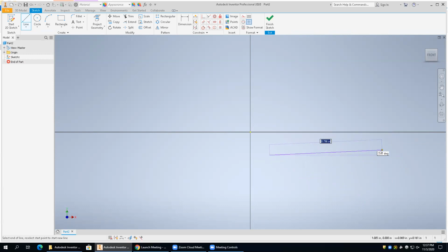So we're just going to drag that out. Don't worry about the distance. But when you see that little symbol, left click. Notice now we can drag this up. And if I drag it up and get it 90 degrees, I'll get another little symbol that's popping out, and that's telling me it's perpendicular. So those are called constraints. There's a vertical constraint. That's a perpendicular constraint. We saw the horizontal constraint. There's all different types of constraints. So we're going to use those constraints as we sketch.